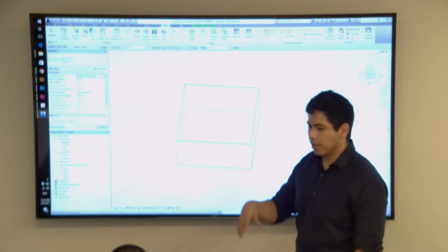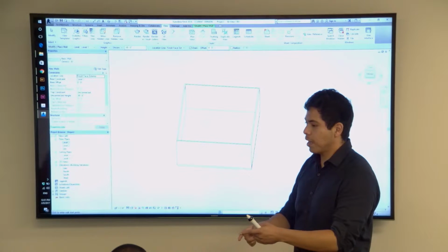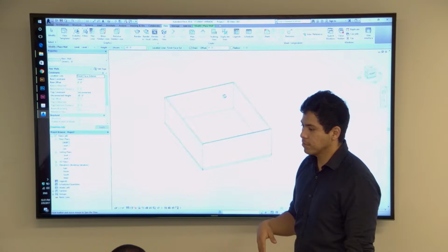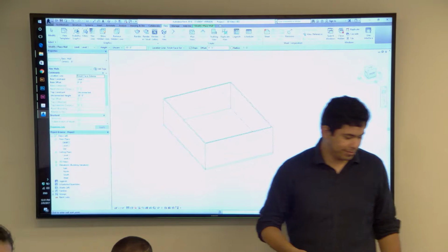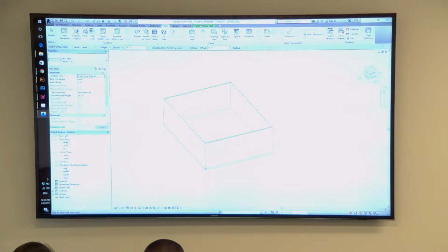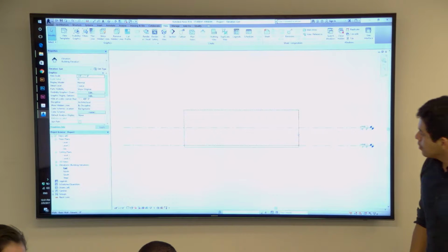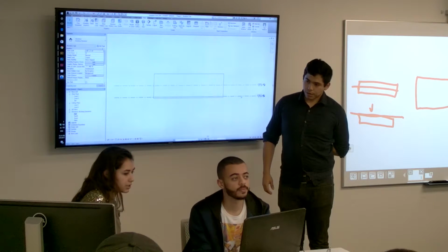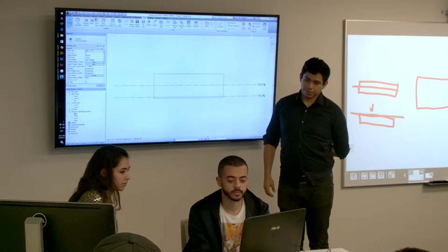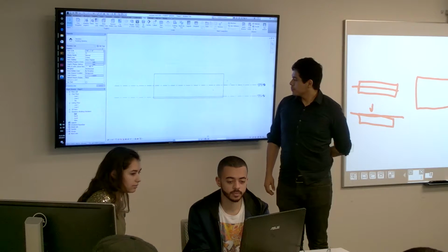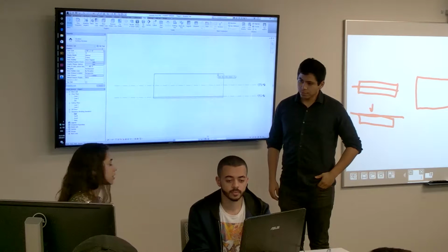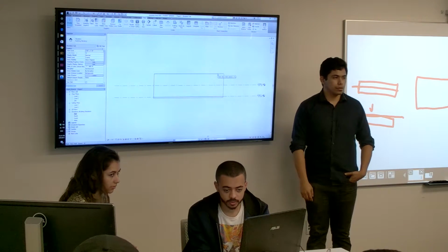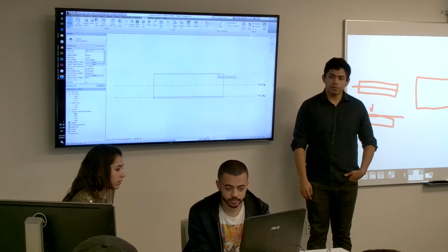Do you want to talk about the roof and how to attach walls to levels? Yeah. All right. So let's make sure that we have levels here. If we click on elevation, I'm just clicking on east for now, we're going to see that we have 2 levels here. This is what we were trying to show earlier. But right now our walls have an automatic 20-foot height, and that's not what we're going to want.